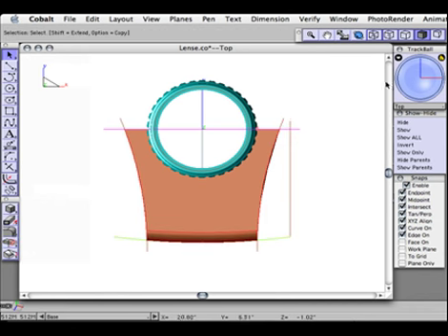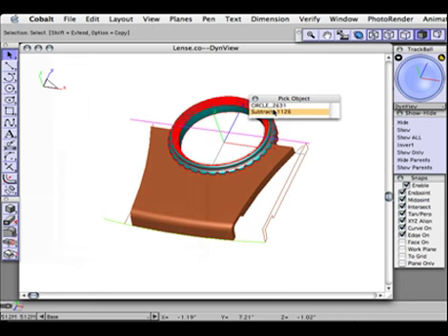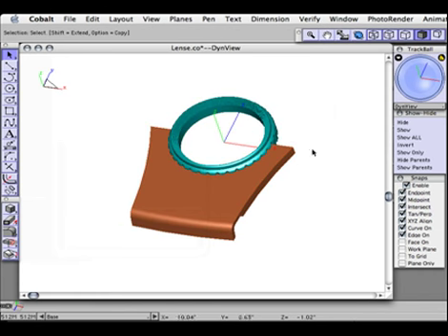Now we have our final shaped piece. Looks good. So I'm simply going to highlight the two solids and click Show Only. Then I'm going to go choose the Union Solid tool. Pick solid to add to. We're going to add to the ring, and then we're going to click the new solid piece, and the two get joined as one. So you see when I click on it, it's all one piece now.